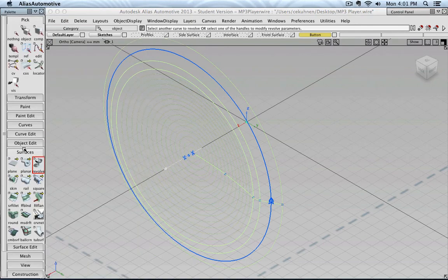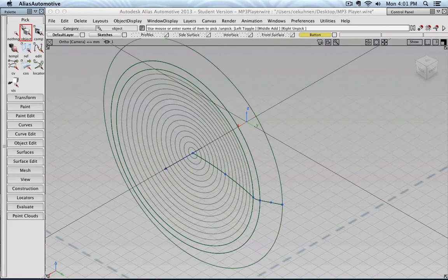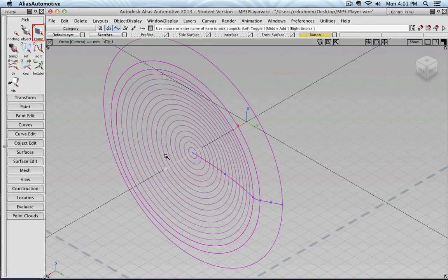And the nice part about this approach is, now I could, for example, go into component select, have my construction options, a vector, and the curve tool turned on. I can click my vector. You see the vector makes the revolve tool or the revolve surface magenta, which means it affects the direction.